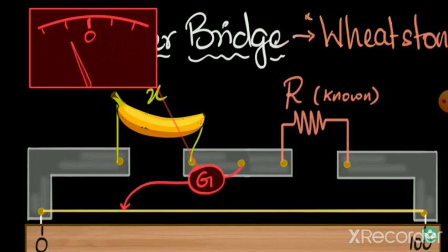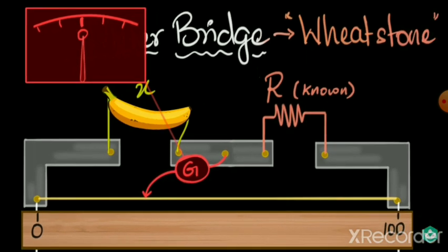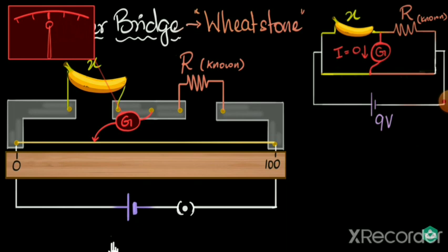Ooh, you can see the galvanometer is coming close to 0. The deflection is going close to 0. Whoops, it overshot. All right, here it is. Now our Wheatstone network is balanced, meaning the ratio of these two resistances must be exactly equal to the ratio of these two parts, the resistances of these two parts of the wire. And so we can now go ahead and calculate it.